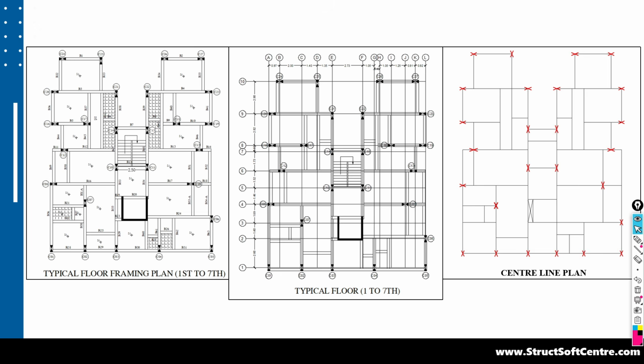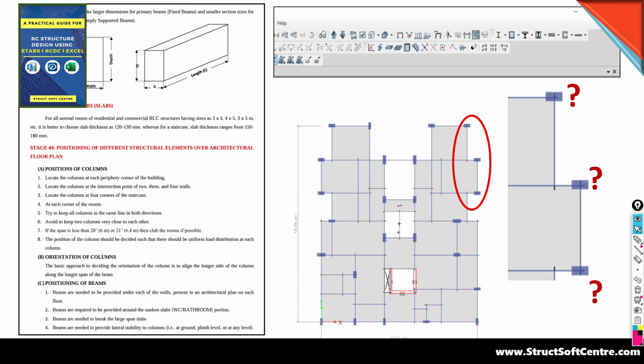Framed structural system, structural wall system, combined structural system, all these types we will discuss in our training program. So this structural framing plan you need to prepare, and before preparing it, you need to decide lots of important things. First is what material property you should choose, what grade of concrete, what grade of steel. There is some concept while deciding the grade of materials.